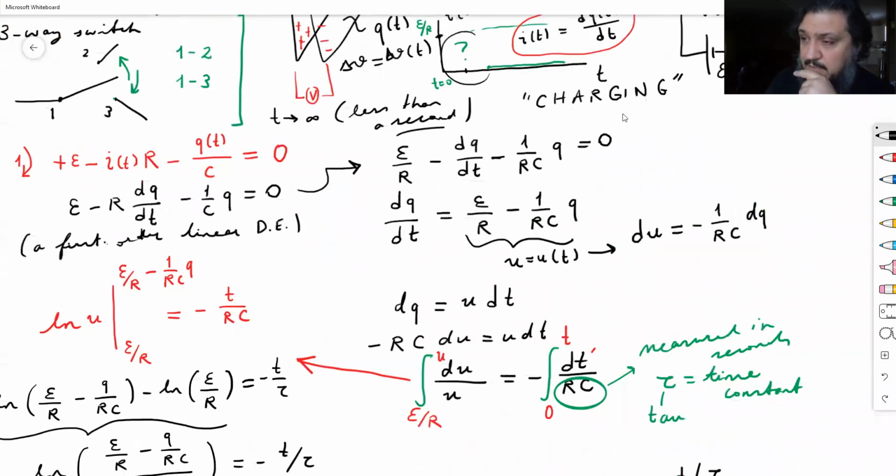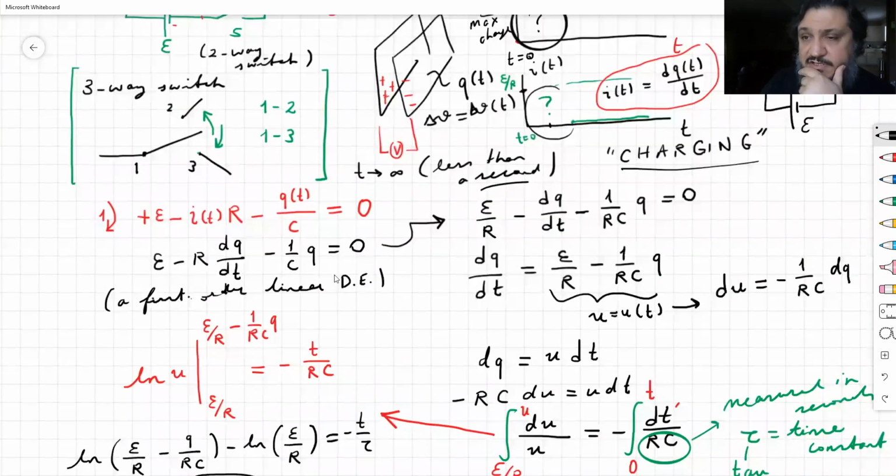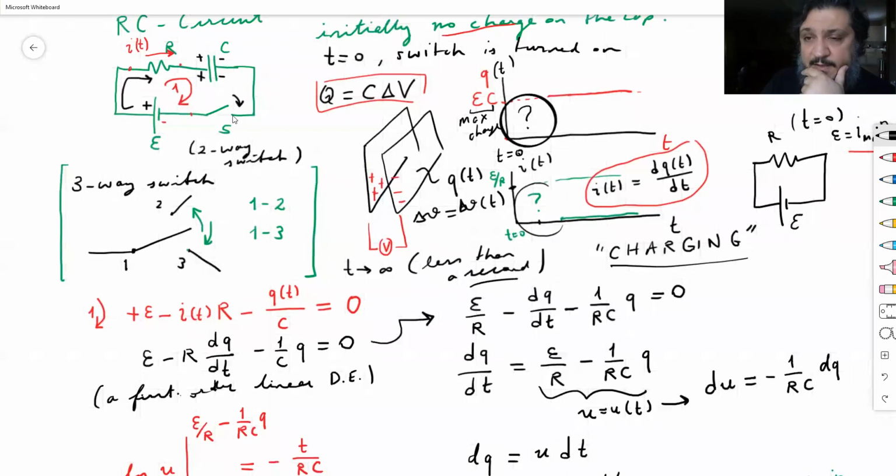All right, what happens when we discharge the capacitor? How are we going to discharge it? Here we have the circuit. Okay, I mean, if you open the switch, you just end up with a battery not connected to anything, and then a resistor without any current through it, but then you have a capacitor with charges, and the charge cannot leave the capacitor. The charges like to be next to the other charges, right? The two plates are oppositely charged, so they stick together. How can we discharge that capacitor? We have to connect those ends again, the ends of the capacitor.